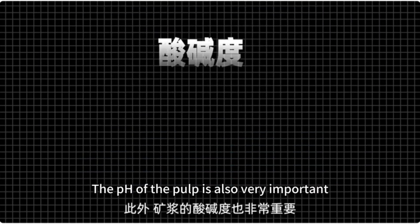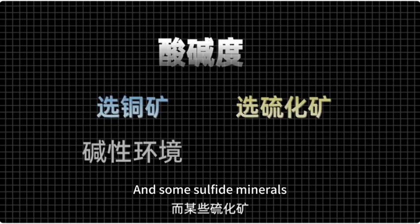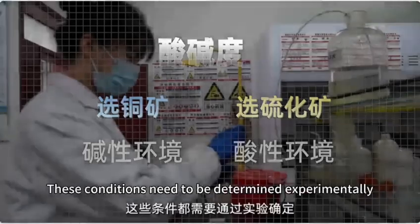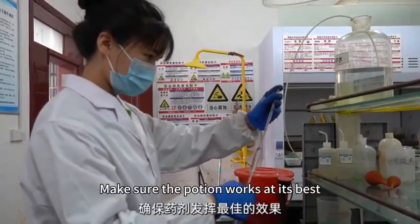In addition, the pH of the pulp is also very important. For example, for copper ore, lime is commonly used to adjust it to alkaline, and some sulfide minerals may require acidic conditions. These conditions need to be determined experimentally to make sure the reagent works at its best.